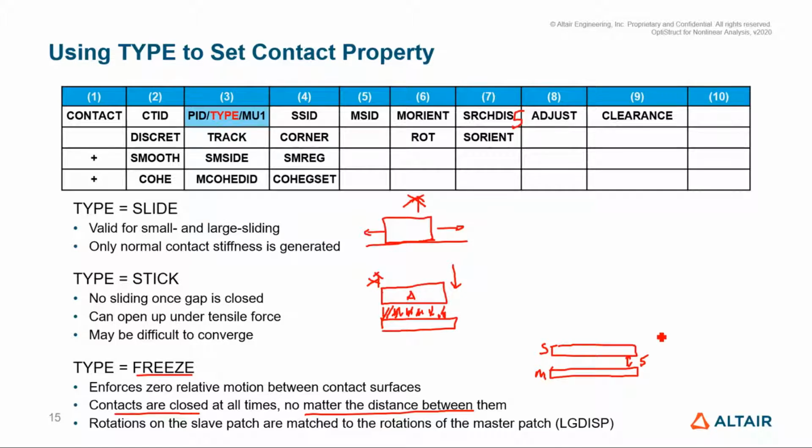All right. So be careful with freeze, especially if your parts have a gap at the beginning. You have to be careful because you will actually establish that contact already. So just take note of this freeze together with this search distance here.